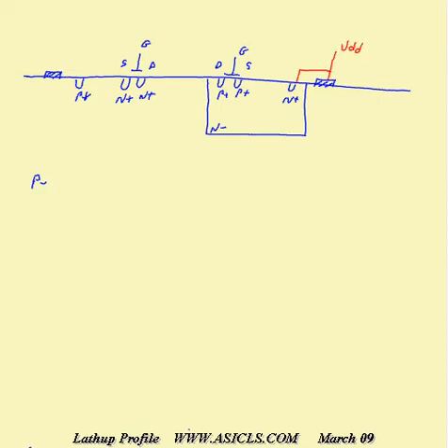The reason we do this is because the N-well forms a diode with the substrate, so we've ensured that by connecting it to VDD that we've reverse biased this diode. We also connect the source of the P-type transistor to VDD. Now we'll connect the source of the N-type transistor and the P-tap to VSS, tying them both low.